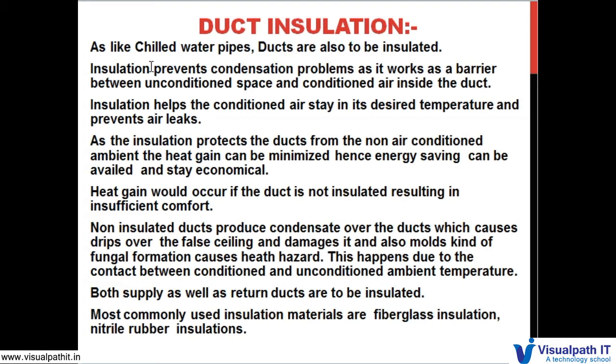Why? Insulation prevents condensation problems, as it works as a barrier between unconditioned space and conditioned air inside the duct. Insulation helps the conditioned air stay at its desired temperature, and also it prevents any leaks. As the insulation protects the ducts from the non-air conditioned ambient, the heat gain can be minimized. Hence, energy savings can be availed and it stays economical.